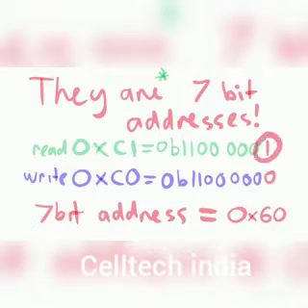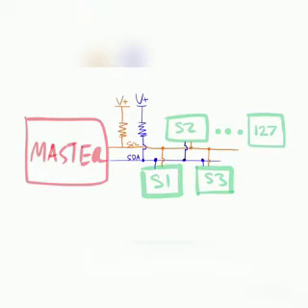After the address is sent, depending on what the read-write bit was, data is either received or it is sent from the microcontroller. If the read-write bit was 1, then the master is receiving data. If it was 0, then the master is sending data. When the master is receiving data, it just leaves the data line alone and allows the slave device to set the data bits. If the data block is not acknowledged by the master, then it's probably the master saying, "Stop reading, there's no more data." If the master was writing data and the slave didn't acknowledge, then there's a problem.